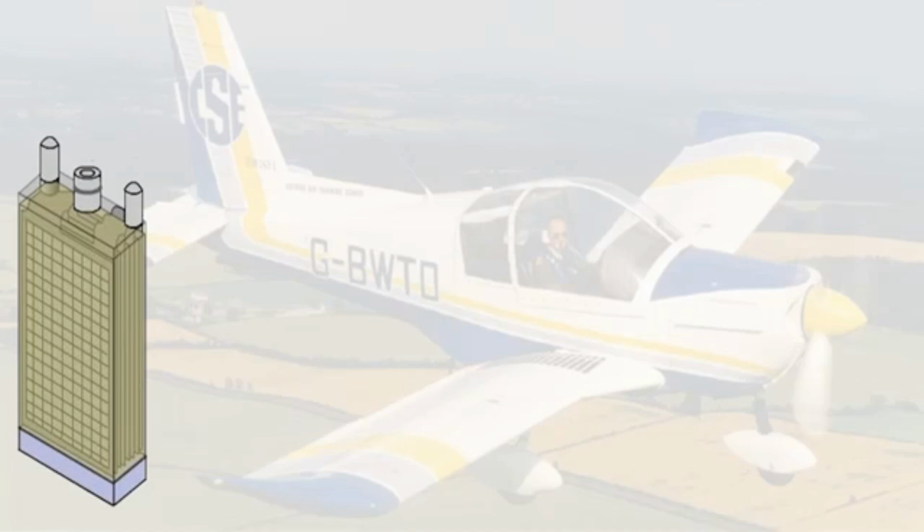Gassing is the formation of hydrogen gas on the plates. The gas must be allowed time to escape through the vent cap of the battery. If too much gas is produced in too short a time, then there's a danger that a build-up of gas pressure could cause the battery to explode, with the subsequent release of the sulfuric acid within.